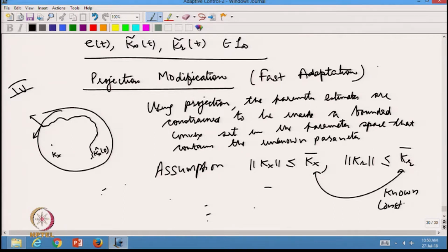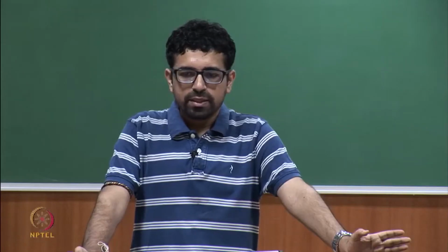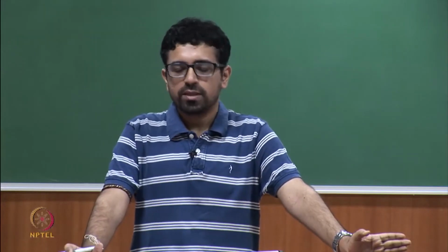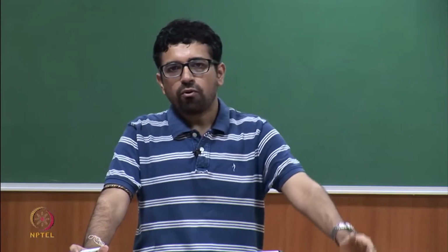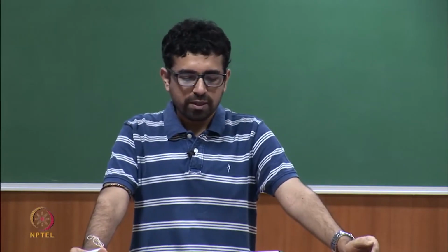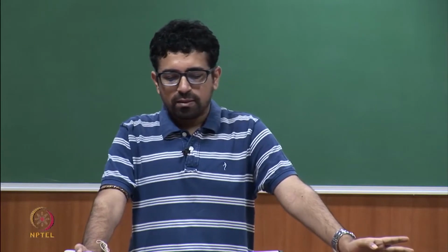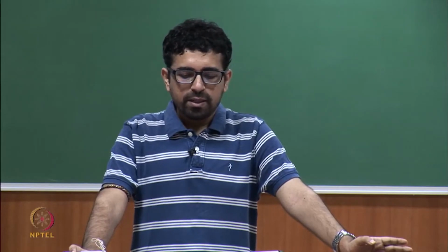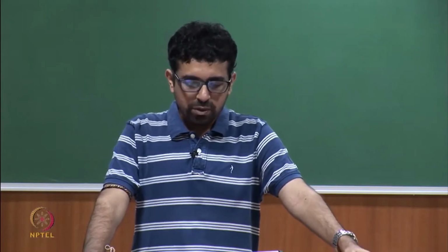This is one limitation, one drawback as compared to, say, E mod or sigma mod, where we do not assume any such thing. In fact, in dead zone also we do not assume an upper bound on these unknown parameters. There we assume that the upper bound on the disturbance is known. So, you see that all these 4 methods that we have covered so far have different flavors, different assumptions, and it depends on the application which one you want to use. Okay.